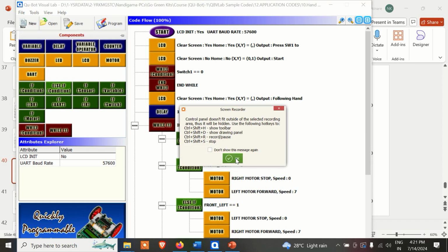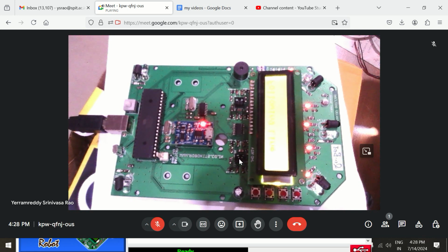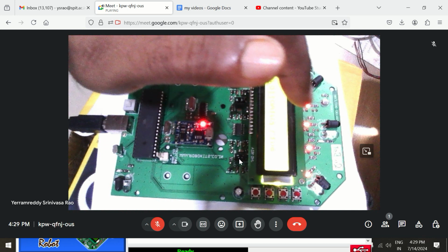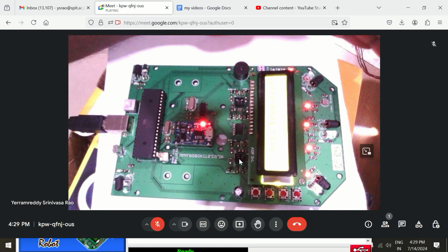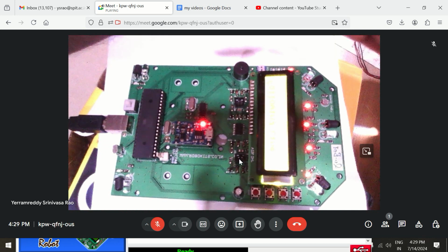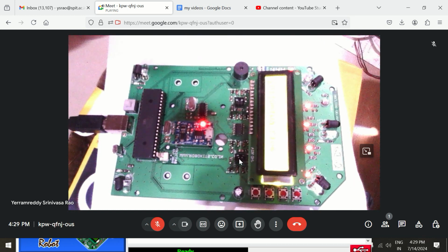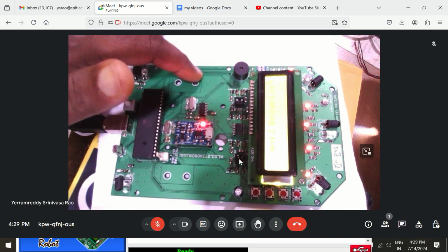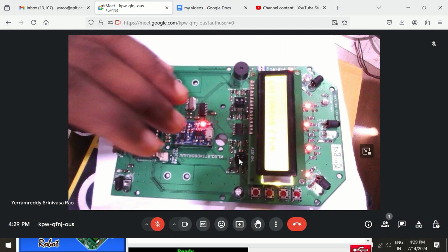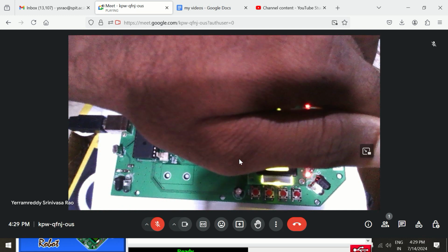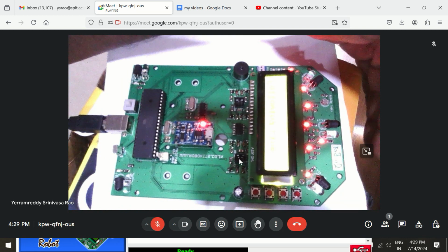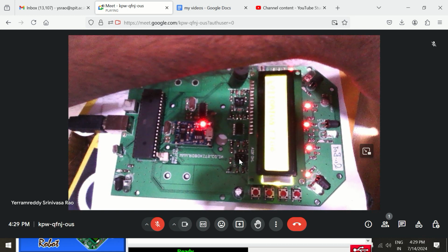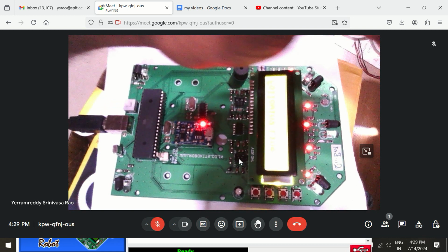All right. So that follow our main means you have 3 front sensors, and whenever you keep your hand in front of the sensor, then since you have the motors, you fix the left motor, right motor, and there is a dummy wheel. So if, for example, you keep your hand in front center, then the vehicle moves in the forward direction. It should move forward.